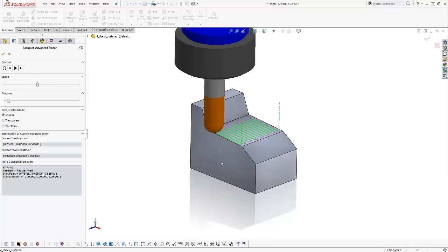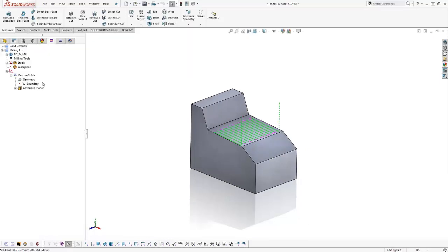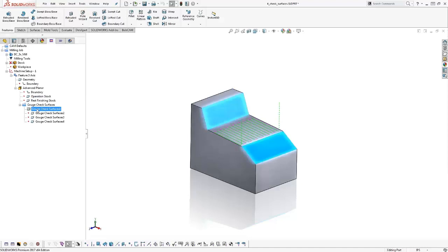Okay. All right, so, the toolpath is driven. This is where, instead of selecting the whole model, we selected a single surface. Maybe it's on a taper angle, down within the part somewhere. We isolated a surface we want to machine, and then what we're doing is we're using our check surfaces to trim that toolpath away. And even though this surface edge is here, when using that as a check surface, you're going to see the tool back up off of that as well. All right. Let's go to the next one here.